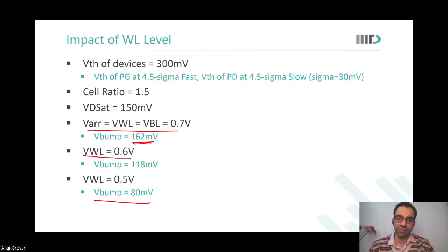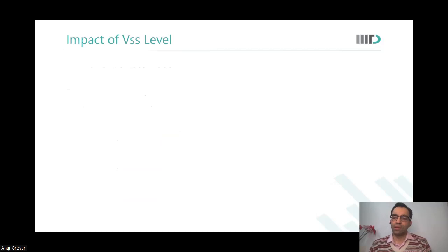Okay. For example, if I'm able to do something and improve any of the parameters, either the cell current or the stability, I would call it a read assist. Yeah, it is assisting. Otherwise, I would have to use larger devices. So anything that I'm using to avoid increasing area by electrically modifying stuff, that is an assist scheme. Okay, sir. Because to me, it seems to be contradictory, but I will look into that.